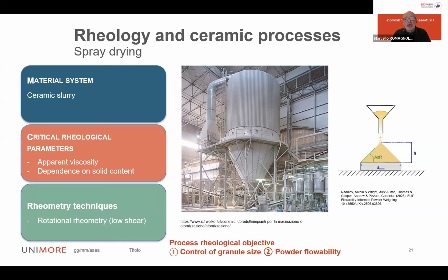We haven't time to talk about the rheology of the powder, which is different from the rheology of the slurry, but this kind of rheology is really important today, especially in the production of big, large tiles that require putting the powders in a homogeneous way over a large area. And also in this case, we can use rotational rheometry.